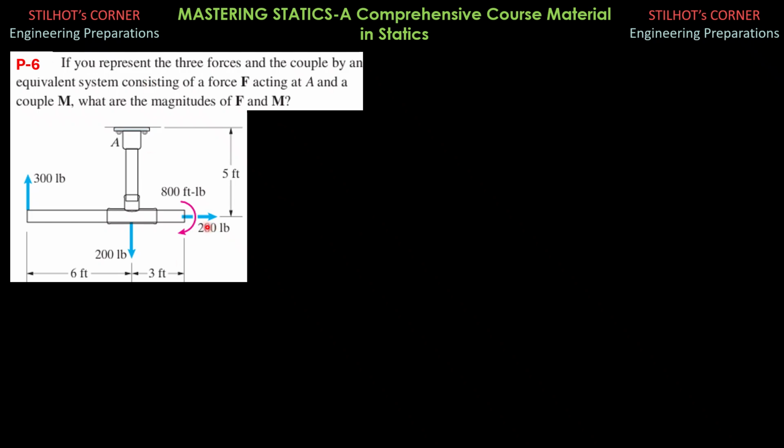So obviously, there's no other horizontal force, so Rx, which is Fx in this case, I'll just represent it with R, then R is equal to F, is 200 pounds, so Rx equals 200 pounds rightward. Then Ry is 300 minus 200, so it is equal to 100 pounds upward.